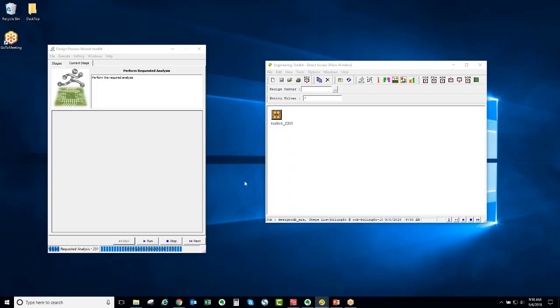Other things that it's looking for in the assembly space, it's looking for component to component based on different package types and sides. There's a whole matrix of rules you can set up, and how when one part rotates up against another part, how close they can be to each other, one package classification to another, how close they can be to each other, how close you can be to test points. There's DFT analysis capability in Valor as well. There's high speed. There's some basic high speed stuff that it can look at.